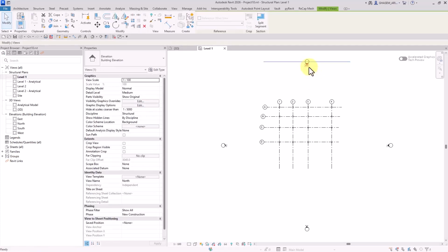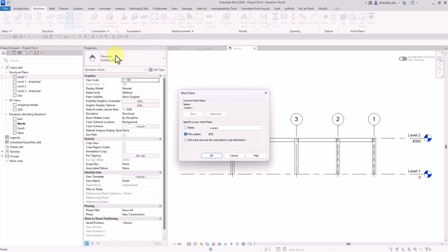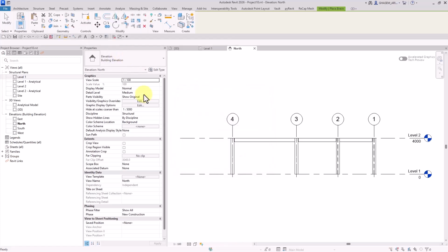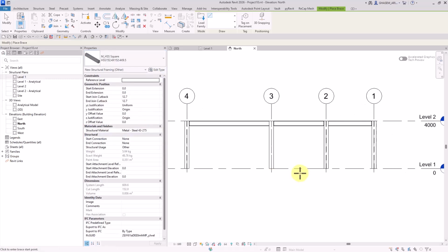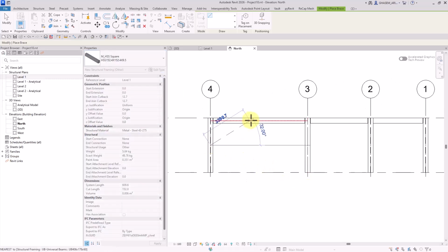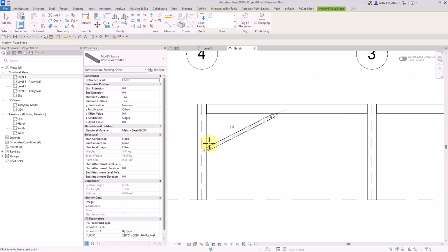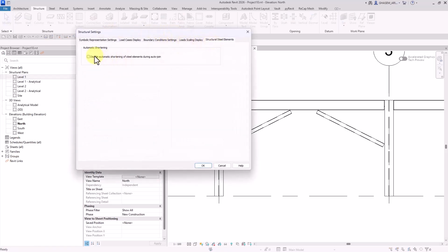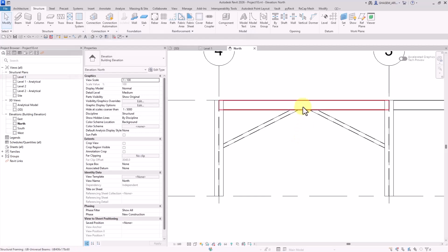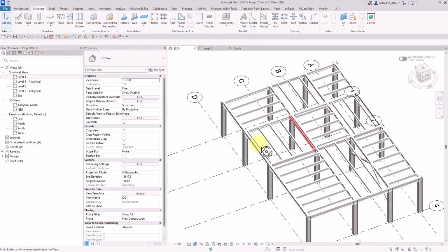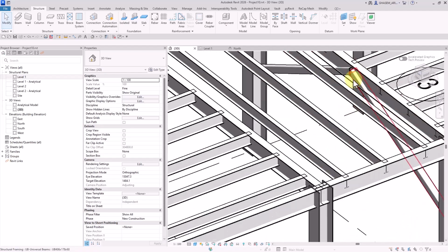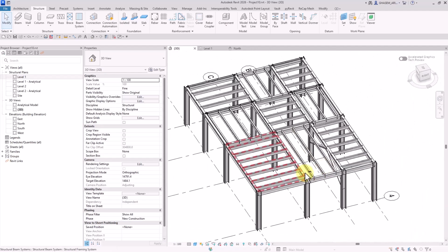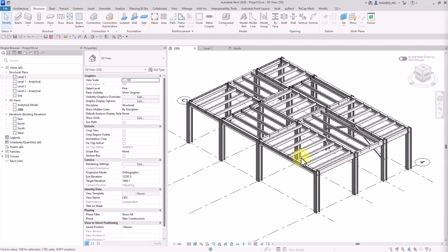We needed a windbreak, right? So I'm going to select brace. For the grid, give me B. Now for the type, I'm going to select the squared one and set this here. Now guys, because of these automatic cuts, later on we might face some problems when we want to connect these. So that's why we need to check this option, Disable Automatic. And now these would be set exactly at the points that you would specify. So again, we can check the geometry better. Now, we have some other changes that we can discuss here.